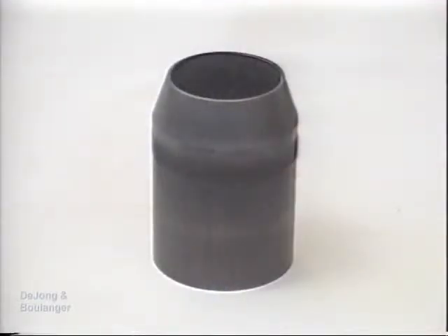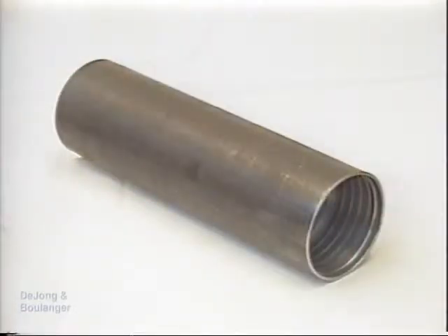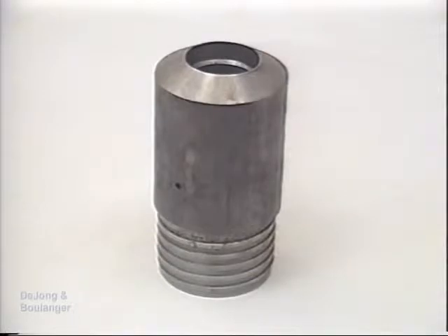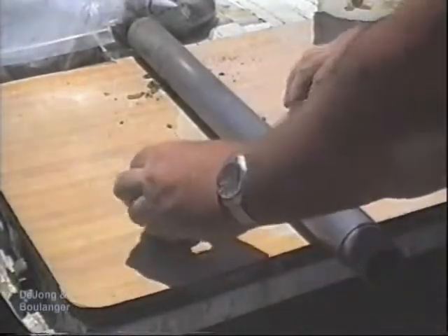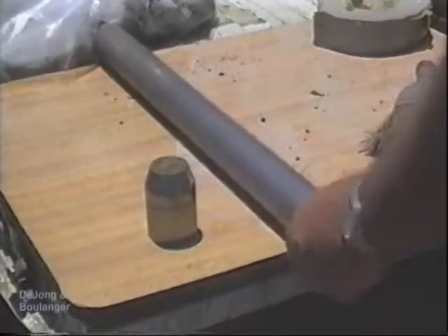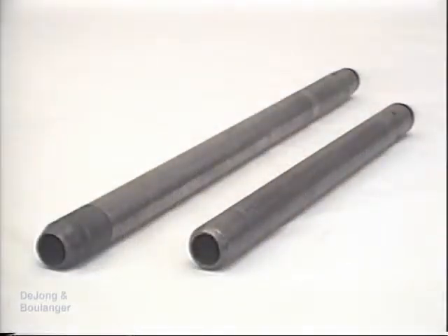The split spoon consists of a barrel shoe, a split barrel or tube, a solid sleeve, and a sampler head. When the sharpened, hardened steel shoe and solid steel sleeve are unscrewed, the two halves of the split spoon may be separated and the sample easily removed. Generally, split spoon samplers are available with inside diameters ranging from 1 3/8 inches to 4 1/2 inches, and in standard lengths of 18 inches to 30 inches. The split spoon sampler, with an outside diameter of 2 inches and an inside diameter of 1 3/8 inches and a length of 24 inches, is the most common in practice.